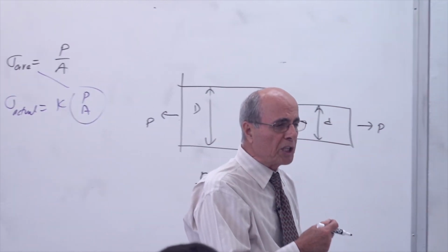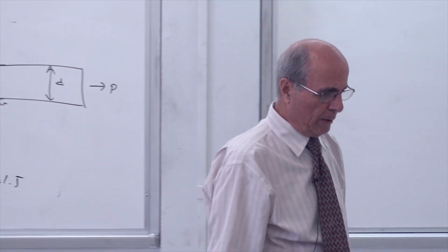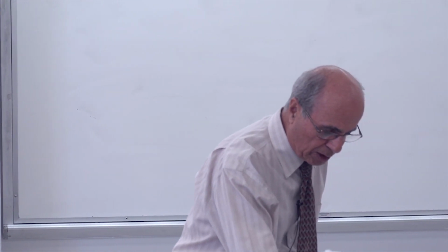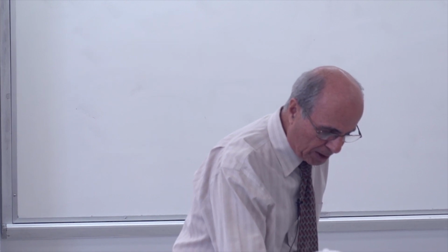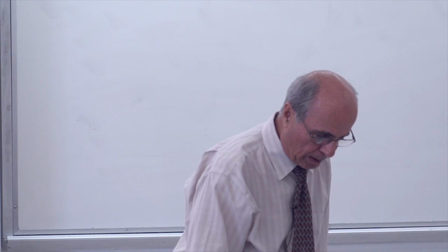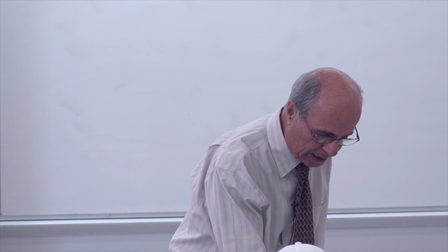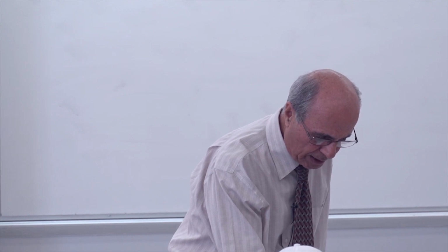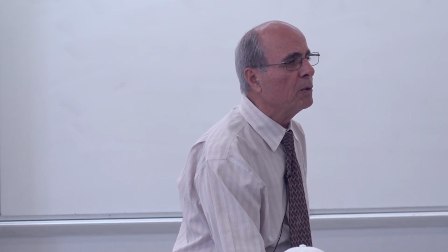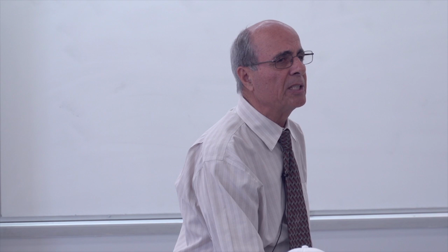So you have to go to the curve of 1.5. Do you see that? You go to 0.12 on the horizontal line. Then you go up until you hit the 1.5. Where is 1.5? Look at the curve, D over d. There is a 2, and the second one from 2 is 1.5. Yes or no? Then what's the number? What do you read? 2.2. Everybody did it?